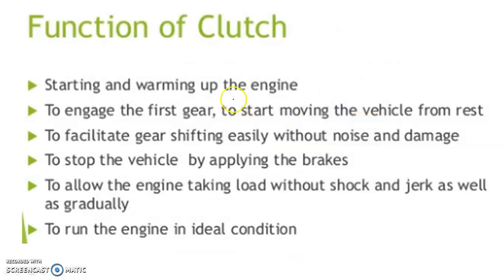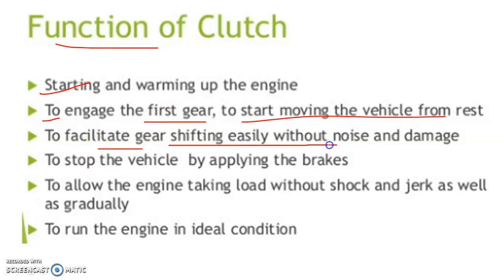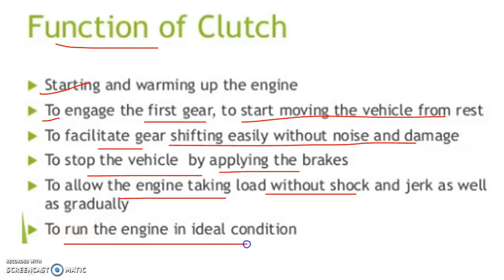After that, let us see the functions of the clutch. What is the first? Starting and warming of the engine, to engage the first gear, to start moving the vehicle from rest, to facilitate gear shifting easily without noise and damage, to stop the vehicle by applying the brakes, to allow the engine to take load without shock and jerk as well as gradually, to run the engine in idle conditions. So these are the different functions of the clutch.